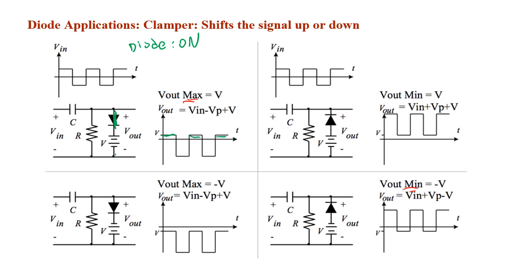And one more thing, notice here you have a charging component, which is the capacitor. So when the diode conducts, or when it is forward biased, the capacitor is going to charge to a value equal to, we'll call it Vc. V stored by the capacitor is going to have a value equal to the peak value of the input.